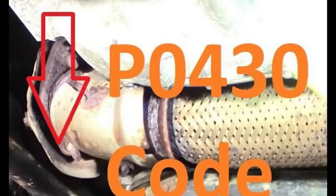The P0420 code on a Nissan is the same as the P0420 code on any other vehicle. It indicates that the catalytic converter is not functioning properly. There are a few ways to test an oxygen sensor for a P0420 code. One way is to use a code reader or scanner to check the oxygen sensor readings. Another way is to use a multimeter to measure the voltage output of the oxygen sensor.